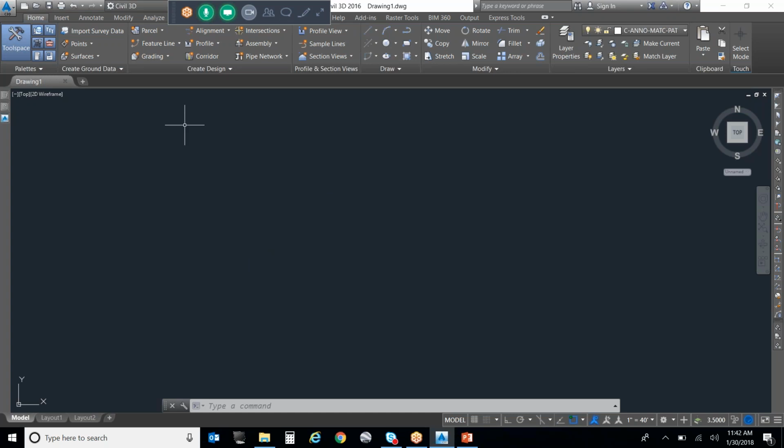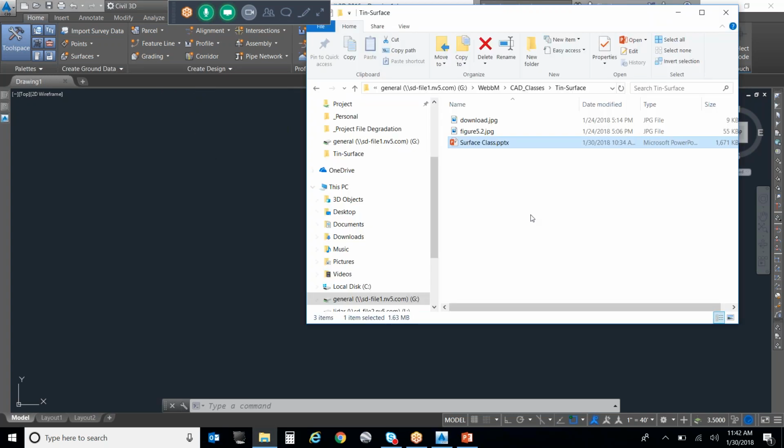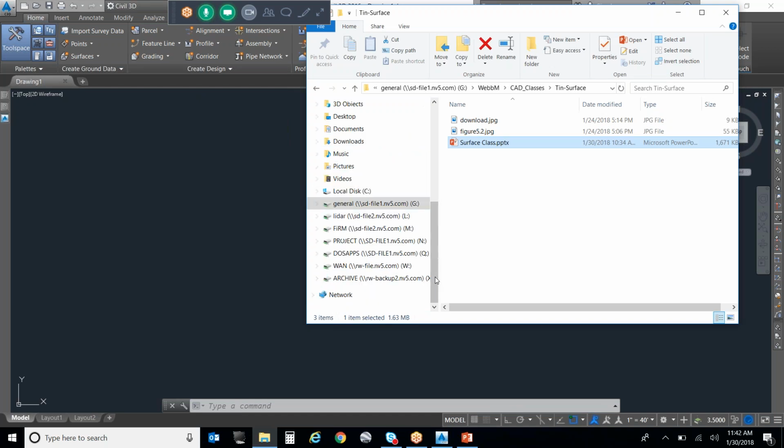So if you have a feature line here and a feature line here, this one will actually dip down and touch this one in terms of your elevation. So it will adjust the elevations of your feature line if they cross while on the same site. So if you have crossing feature lines or overlapping feature lines, they need to be on different sites. Otherwise, they will change elevations.